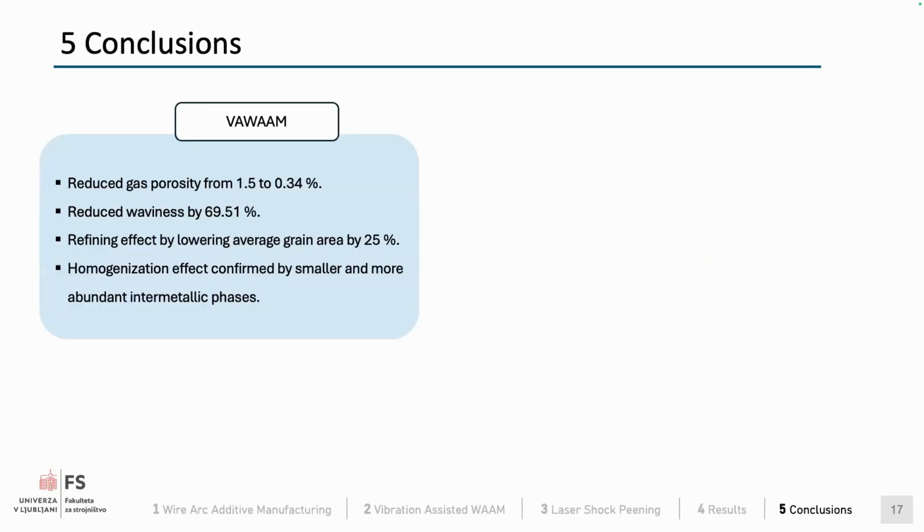In the vibration-assisted one, we successfully reduced the gas porosity, reduced the waviness, got some refining effect by lowering the average grain area by 25%. And we also confirmed the homogenization effect induced by vibrations.